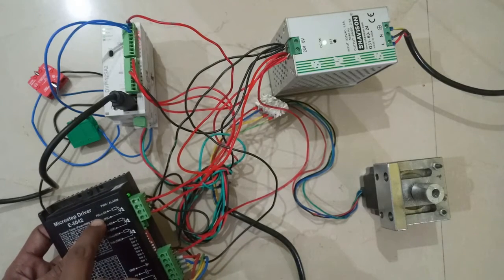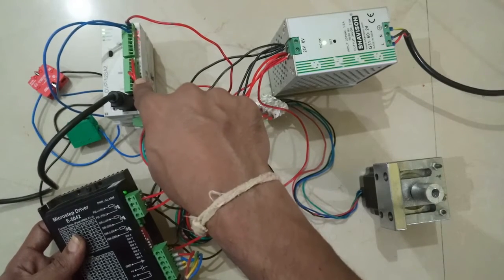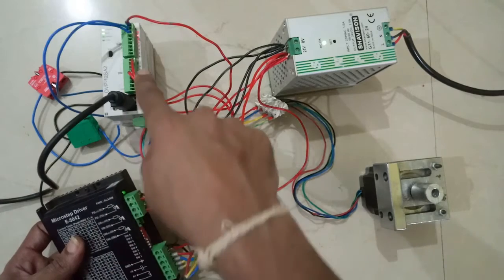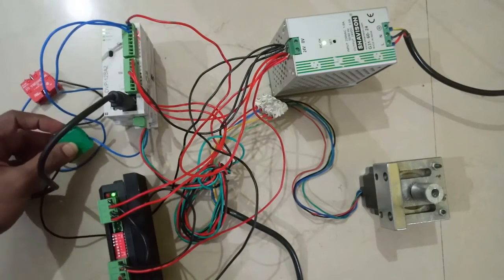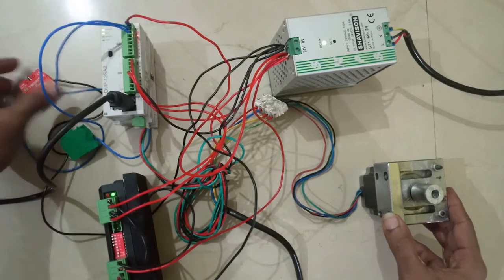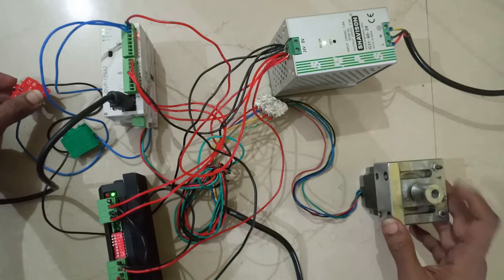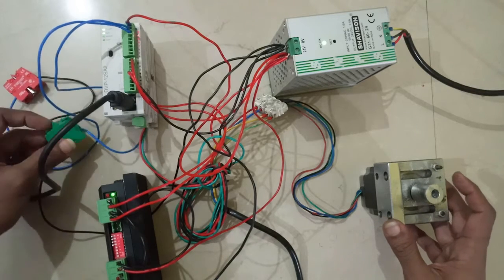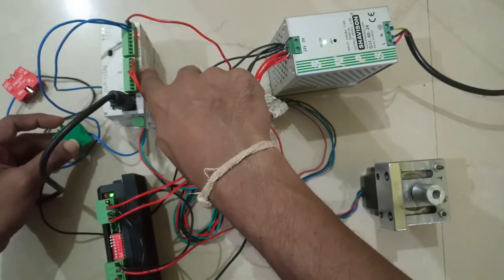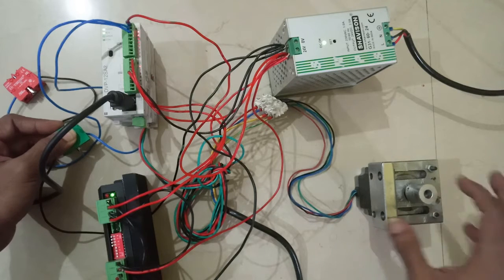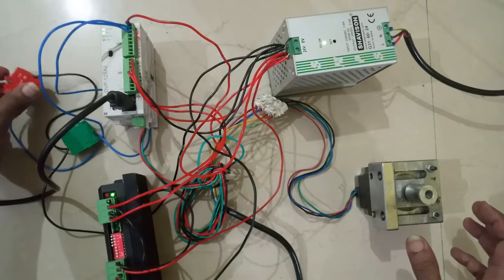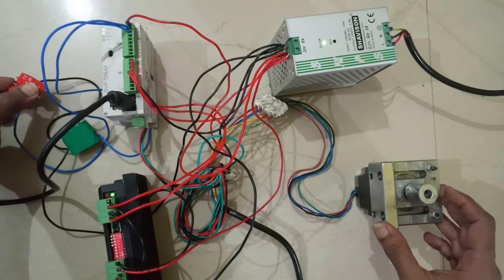So this pulse we have connected to the output of the PLC, that is Y0, and for direction we have connected pin number 2, that is Y1. So when we press this switch, the motor will run clockwise, and when this switch is pressed, the motor will run anti-clockwise, or you can say counterclockwise. So here you can see this LED of Y0 will glow when I press this, and this motor will run. So here you can see it is rotating in clockwise direction, and when I press this red switch, it rotates at